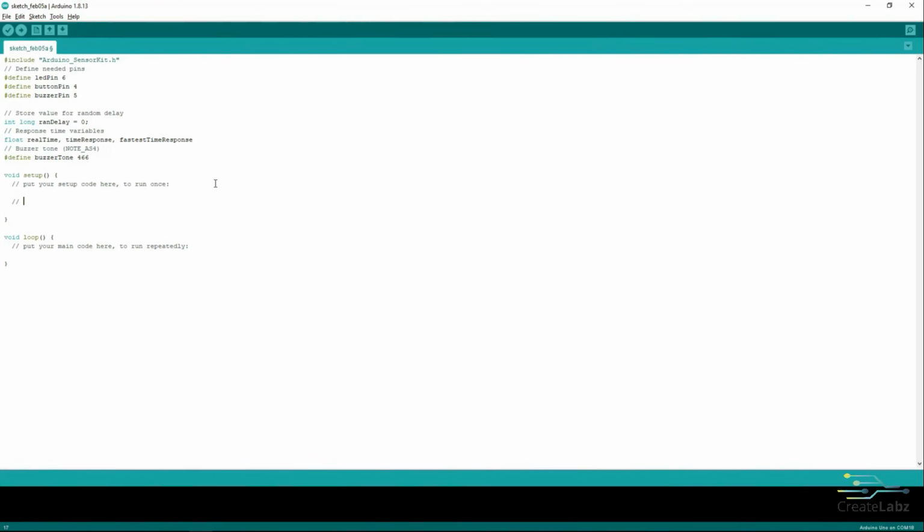Now go to the setup function and let us initialize the OLED display. To initialize this, simply put oled.begin. Set the OLED display orientation to rotate to 180 degrees by using the Set Flip mode to True. Also, to set the OLED font, use oled.setFont.